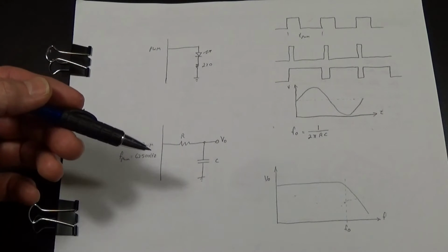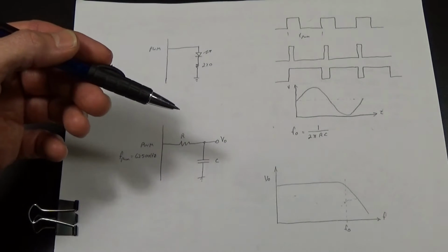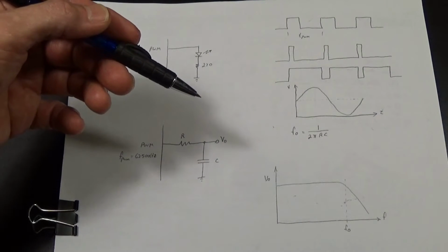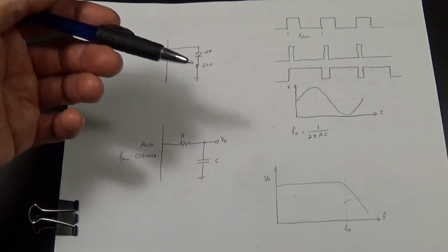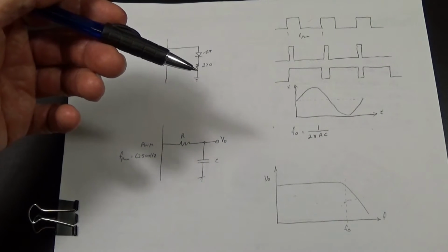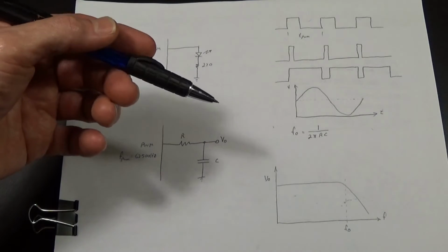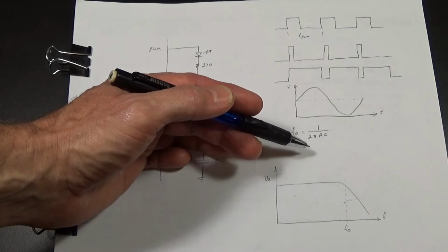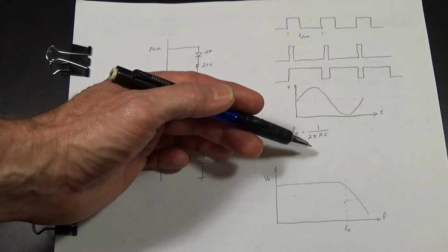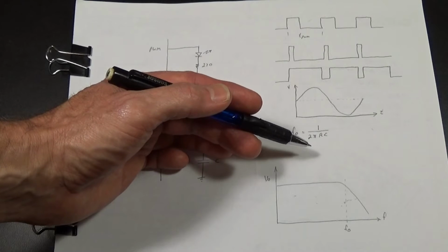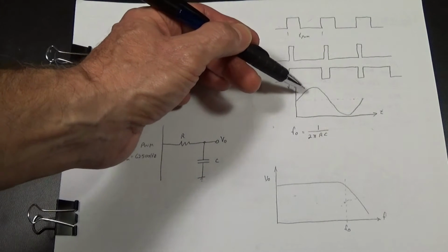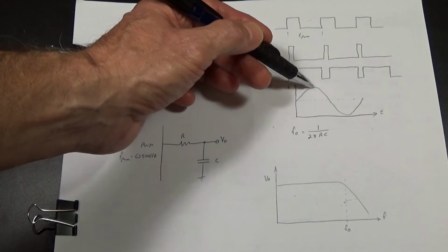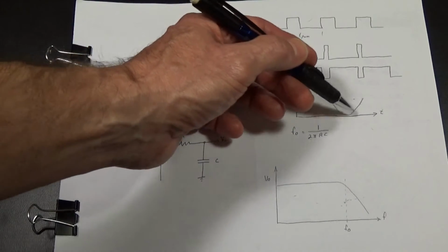So we have this counter that's being incremented, and we simply add a fixed value 50,000 times a second. That works out to 20 microseconds. 1 over 50 kilohertz is 20 microseconds. So every 20 microseconds I take a fixed number and add it to that 16-bit counter. Then I take that value and massage it a little bit, and use it as an index to get a value out of the sine table to give me an output voltage, and I put it into the PWM to give me this output voltage.